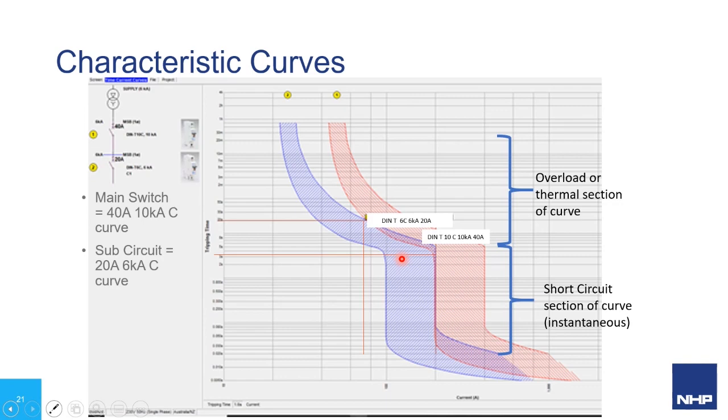We can see that the breakers do overlap slightly between the 3-second and 20-second time coordinates at overcurrent values between 75 and 200 amps. This means that selectivity theoretically can only be achieved up to 75 amps. Above this level, given an overcurrent, the upstream main switch may also trip. There are many levels of fault that need to be considered if we are to increase our system supply reliability.